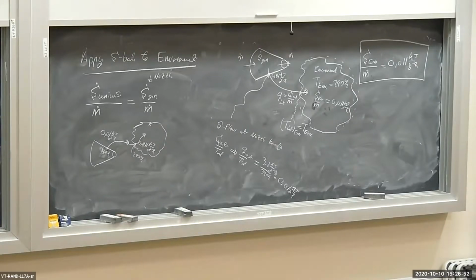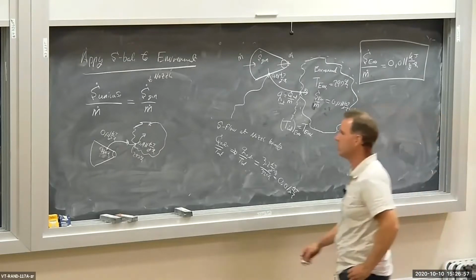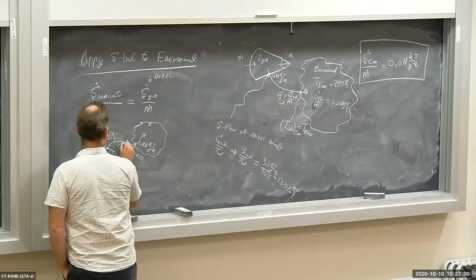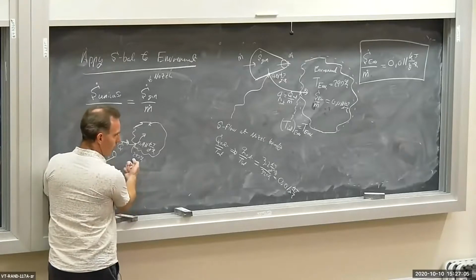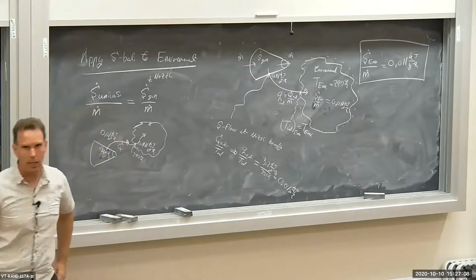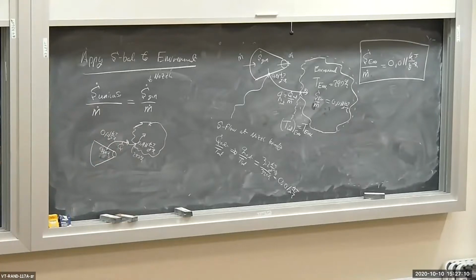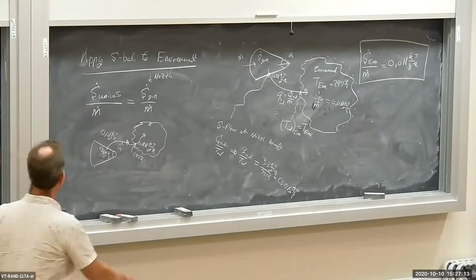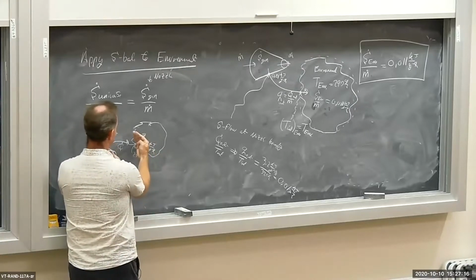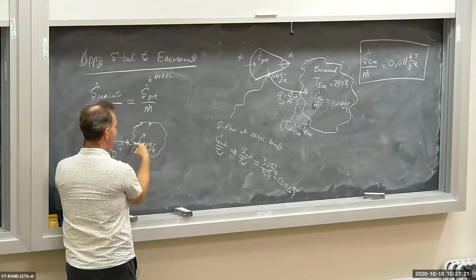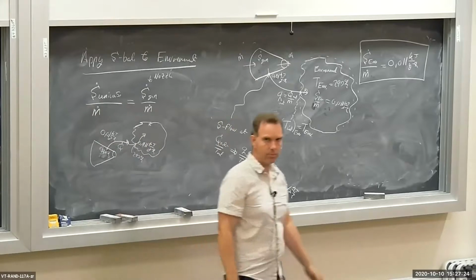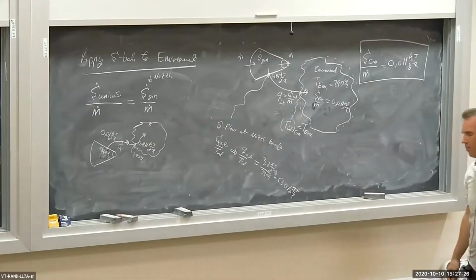It is irreversible. We have heat transfer, Q dot out, from hot to cold across a finite temperature difference, 320 to 293. That is irreversible, therefore there's entropy being generated in this region. Entropy is being generated between the nozzle and the environment, due to finite temperature difference.